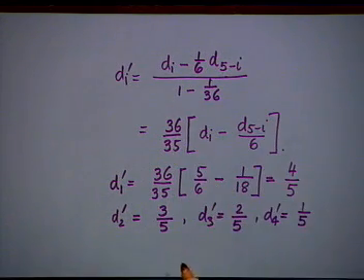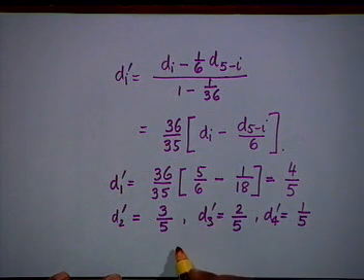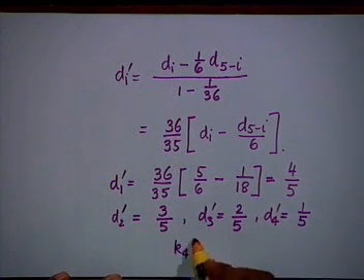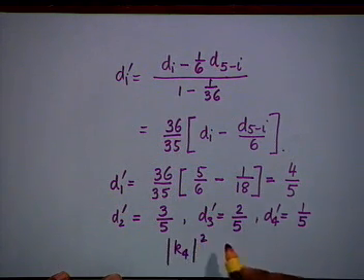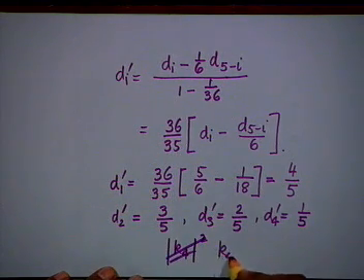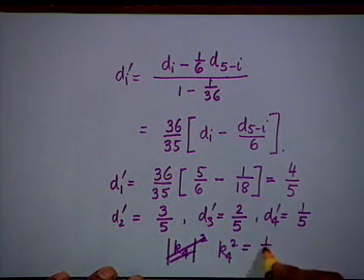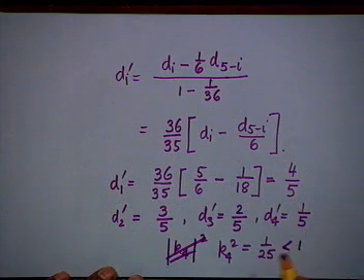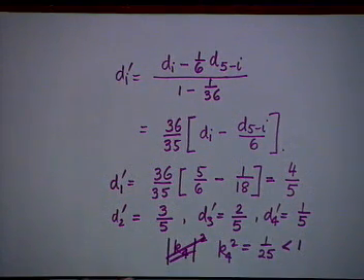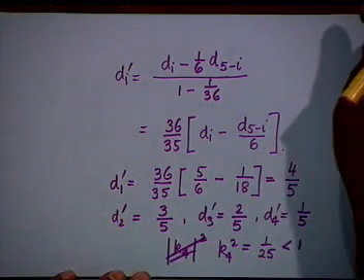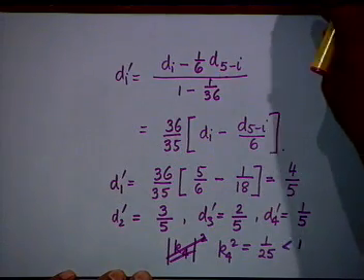The same formula. Okay. Now therefore k4 squared, no, not magnitude squared, k4 squared is equal to 1 over 25, which is less than 1. The test has not failed yet. Okay. So we are encouraged to go to the next step, that is, you have to compute A3.